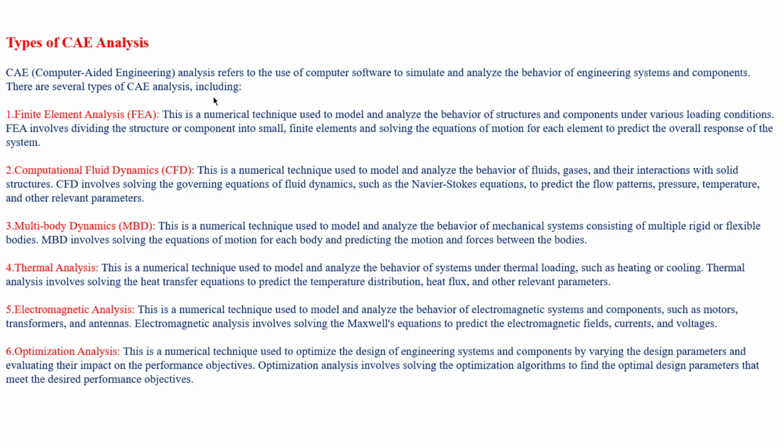When it comes to CAE, we have the finite element analysis, FEA, right? We have the CFD, computational fluid dynamics, where the Navier-Stokes equations are used. MBD analysis, the multi-body dynamics. Okay, very important. Here we're going to deal with multiple rigid and flexible bodies. Then we have the thermal analysis, a separate module. Okay, electromagnetic analysis and the optimization analysis. Here the design optimization and the topology optimization come into account.